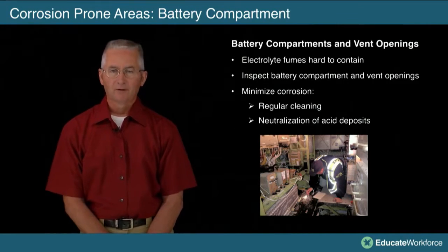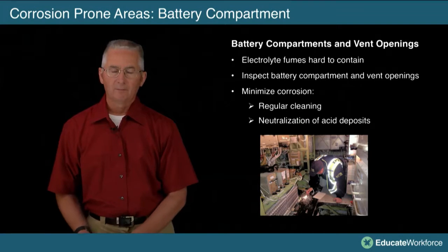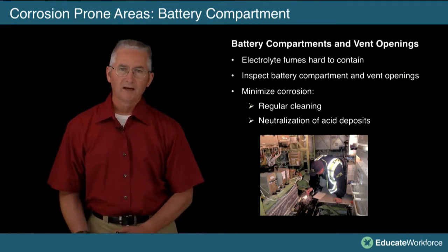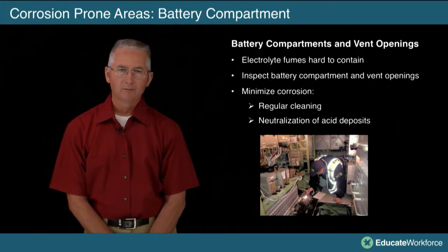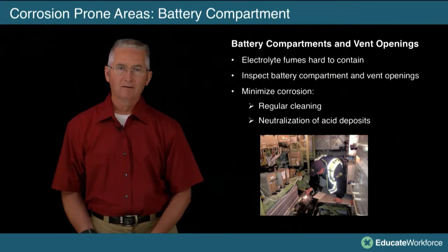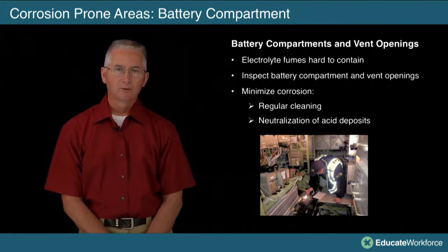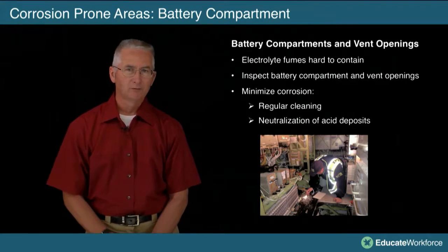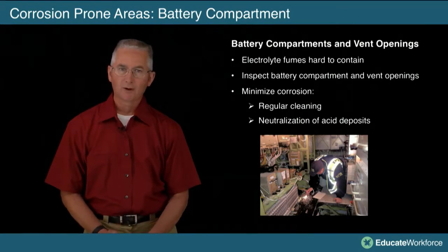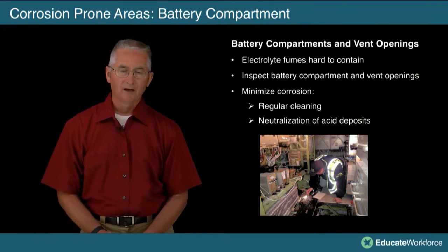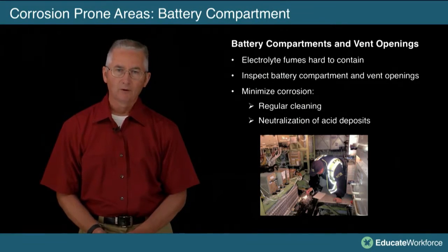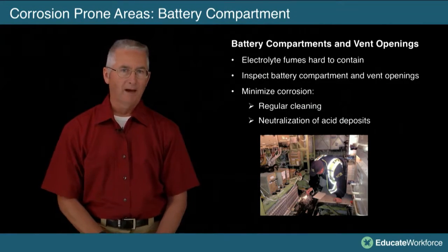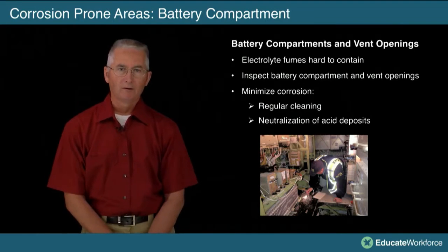The battery compartments and battery openings are another area prone to corrosion. When you're charging your batteries, you're creating battery fumes. The battery fumes are acidic. Whether you have a NiCad battery or a lead acid battery, you're still producing fumes. There should be something in that battery compartment that is going to catch and neutralize those fumes, some type of sump jar. If you have a lead acid battery, it'll have bicarbonate soda or a baking soda impregnated pad. The fumes go through the pad and are neutralized before they go out to the system.